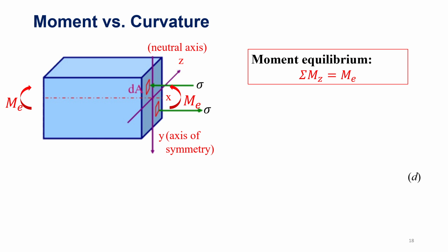How about the moment equilibrium? In the directions x and y, we have a total moment of 0. It's only in the direction z that the total moment equals the applied moment, which is Me here.